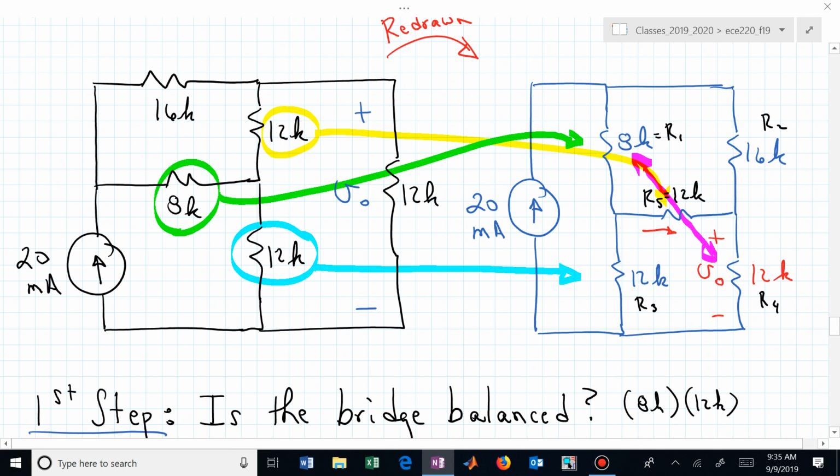So put on your virtual reality glasses, and what I want you to see is I5 is equal to 0. If I5 is equal to 0, what do you now need to do? Just erase that resistor. You can erase that resistor virtually because there's no current through it, there's no voltage across it. That means that this node that I'm calling the odd node and the even node, O and E, what's the voltage dropped across those?